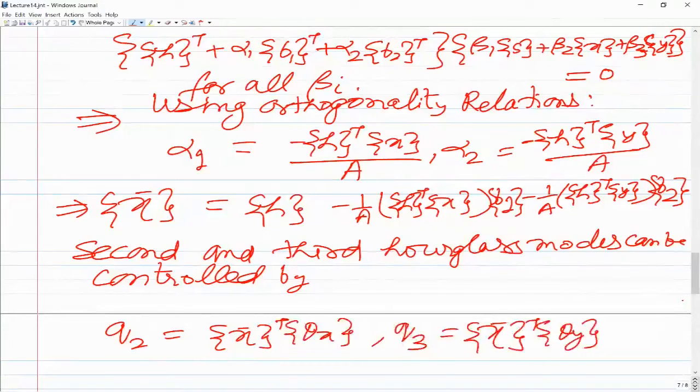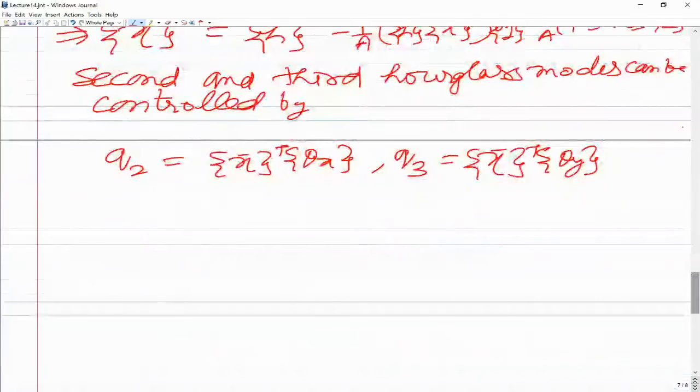So like that, you can take these modes now. Once we define these generalized displacements q1, q2 and q3, then we talk of corresponding generalized forces. Because ultimately, corresponding to the hourglass deformation, we have to add the corresponding forces, so that these hourglass modes are registered, they are not activated.